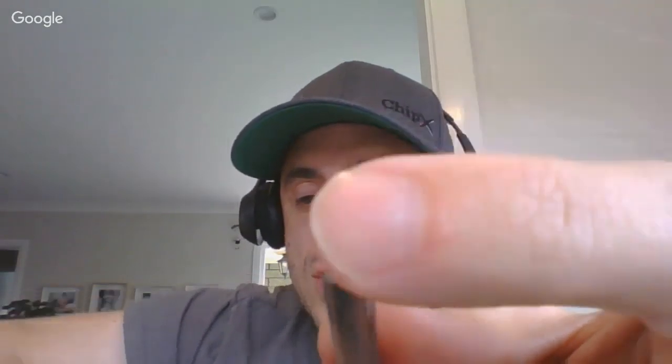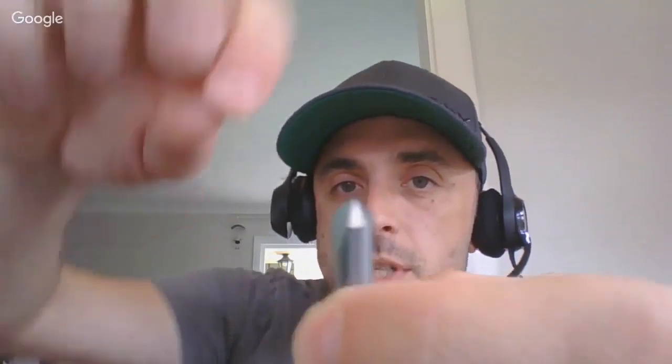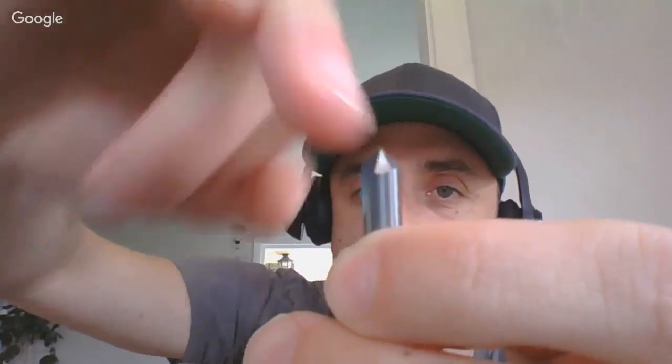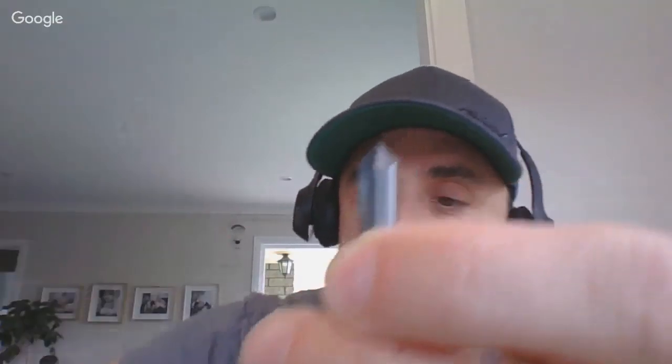If you take it to the extreme, and it is just a hypothetical thing, if that point is actually 0 millimeters diameter, then it doesn't matter how fast you spin it, it's not actually moving, because a point that's 0 diameter can't be turning. So the actual speed that the metal is moving through the material you're cutting is based on the diameter, and the larger the diameter, the faster the surface speed. So when you start getting down to small tools, you have to be spinning them really, really fast.